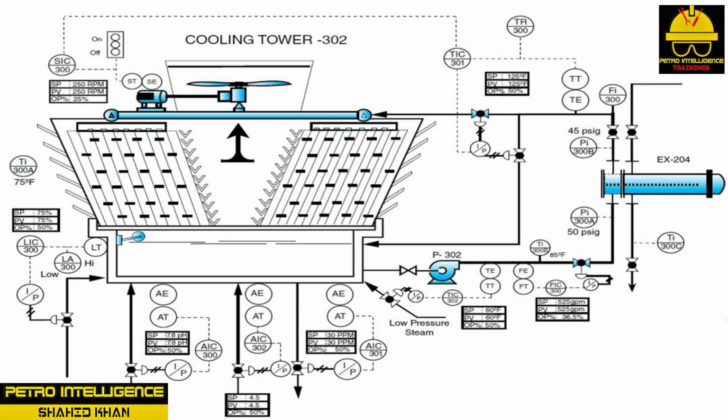Blowdown draw-off, or blowdown, is primarily used to control the buildup or concentration of minerals in the recirculation water. The blowdown system is designed to control the level of suspended solids in the water basin. High levels of suspended solids will cause fouling. Blowdown is closely related to the term concentration cycles. Blowdown refers to automatically removing 7 to 10% of the water in the water basin and replacing it with fresh water. In most cases, the water makeup system runs continuously due to evaporative losses, drift losses, and draw-off.